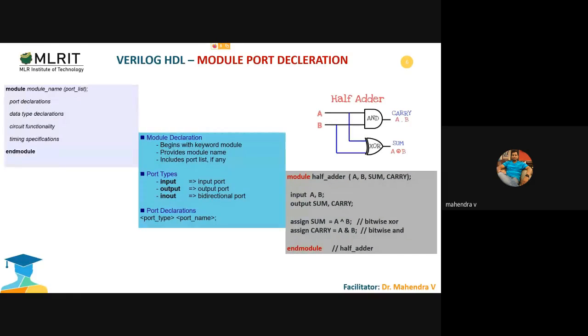That was the mistake I made. While writing the program for the multiplexer, I named the module 2-to-1 multiplexer. The name started with 2, so instead of a letter I kept a number. That was the error, continuously thrown. Finally, after two months, I found that was the error.